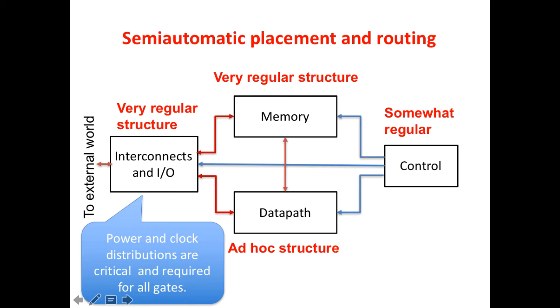On the other hand, the data path is on a relative basis much less regular than the control, because in the data path we have specific operations and combinatorial functions, so typically for each specific operation, for each specific combinatorial function, we have specific circuits. So also the interconnection between the different blocks is ad hoc for each particular function that has to be implemented.